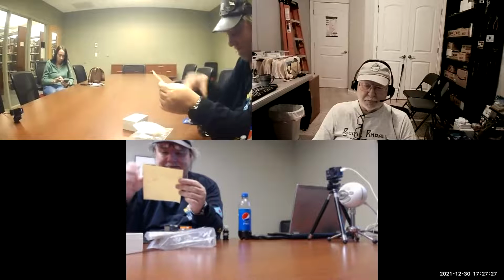What's this, Jim? It's an antenna tuner. Oh, yeah, okay. Yeah, you talked about that a couple of weeks ago. It's a kit. It's a down on the metal solder kind of thing. The main piece of it is the toroid that you wind yourself. You put 10 windings through it, and then you do 2, 2, 3, 2, 4, 2, 1. It has a 12 position switch. Then you solder it to the 12 position switch, and then you have a couple of variable capacitors.